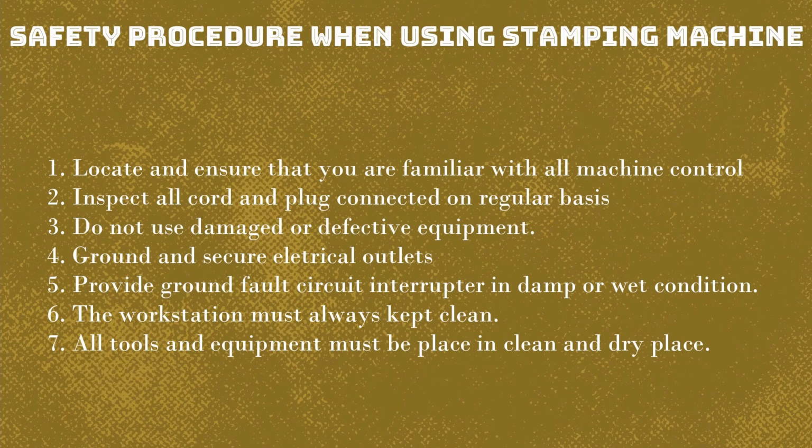Third, do not use damaged or defective equipment. Four, ground and secure electrical outlets. Five, provide a ground fault circuit interrupter in damp or wet conditions.